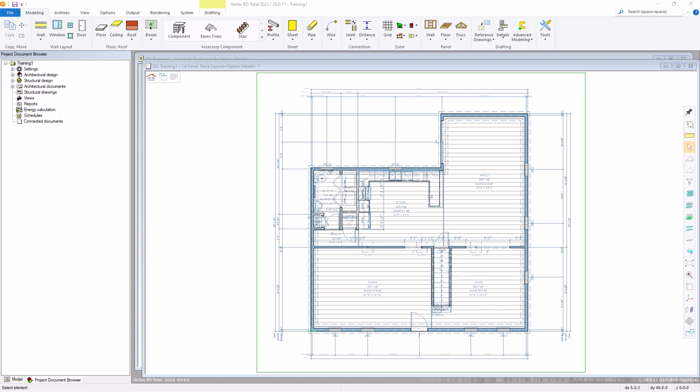Before we generate our floor framing, we need to determine the direction of the floor joists and how they will be supported. We'll have the joists run front to back. Over in this area, we'll have them run left to right. For support beams, we'll add a drop beam over the family room. We'll add a flush beam to support the floor joists along this wall. We have 3 columns in the basement that will support that member.